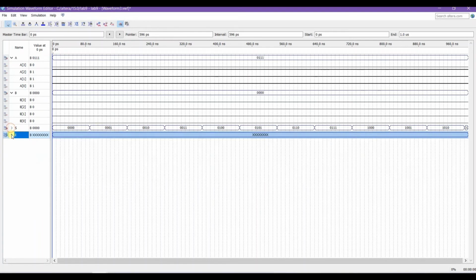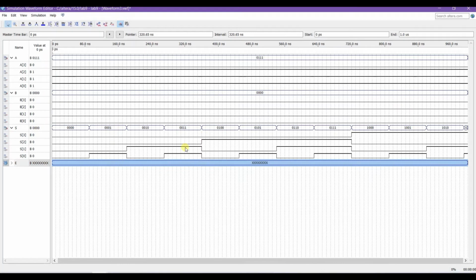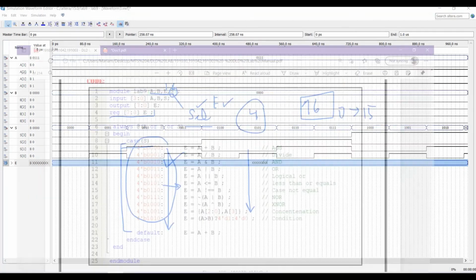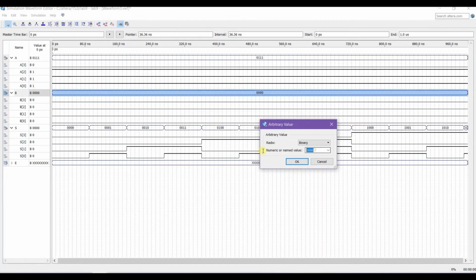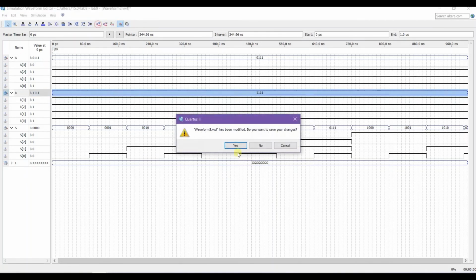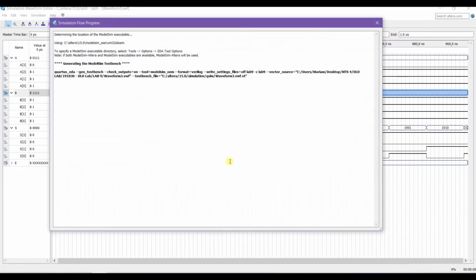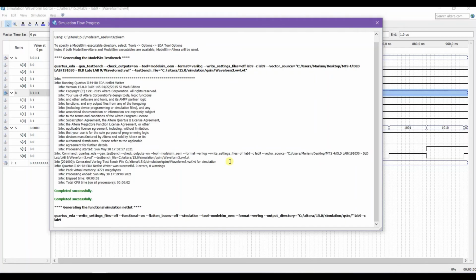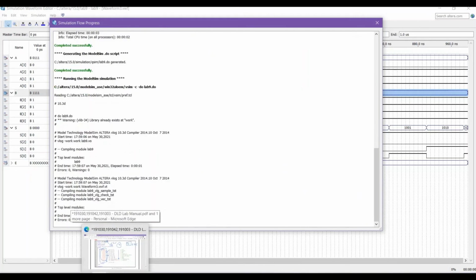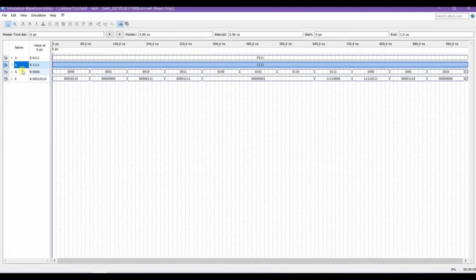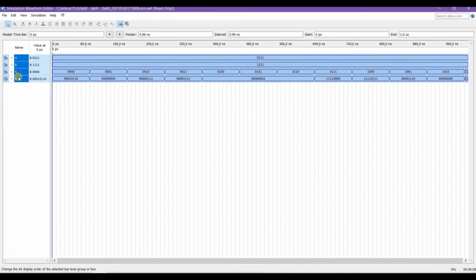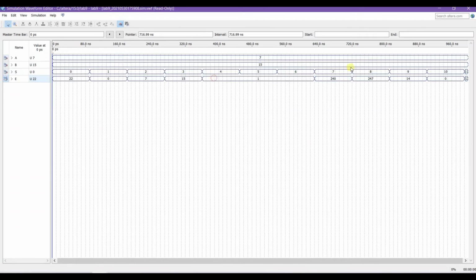So we can also define it that way, as it is a selection pin, so we define it like 0000 and 0001, then 0001, and this is how this increases. So I already run this input. If I run it here, if I define this also as a 1111 and then just run it, yes, save. Now wait for a second here. And this is done. So this is the compilation of it. If you want me to do it in the binary radix, I define it as unsigned decimal. So this is how this forms.